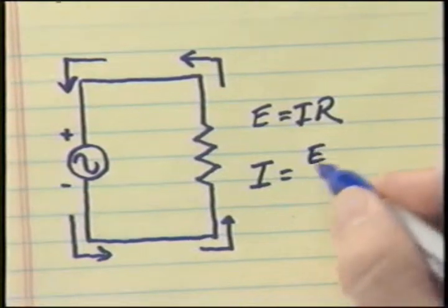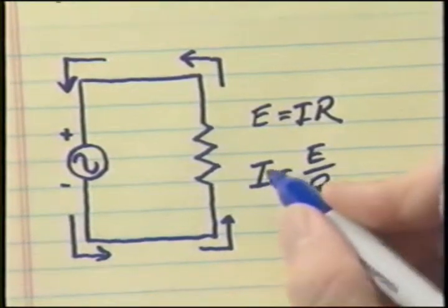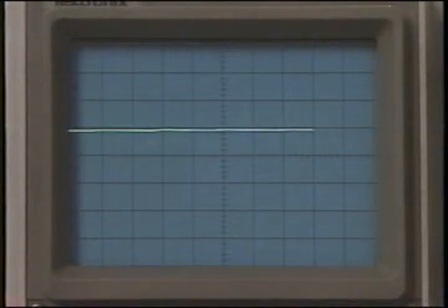The only conceptual difference between the AC and DC applications of Ohm's law is that while the voltage and current values in a DC circuit can be expected to remain constant, in an AC circuit these values are constantly changing. But for an instantaneous moment in a given cycle, the value of the current flowing at that instant is directly proportional to the magnitude of the voltage at that same instant. Since all direct current rules and laws apply to alternating current resistive circuits, the AC power may be calculated from the measured voltage and current.